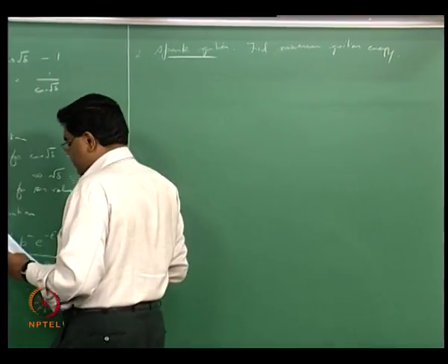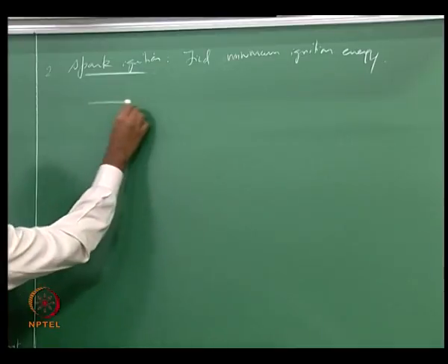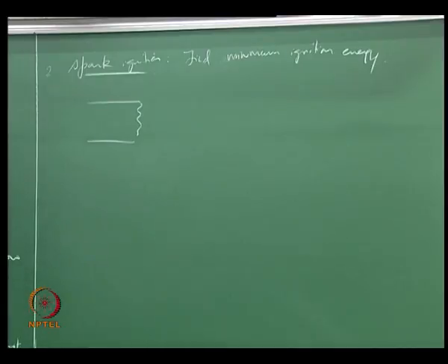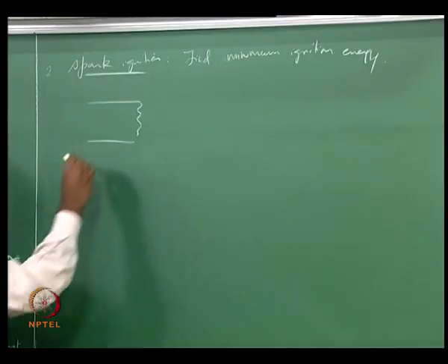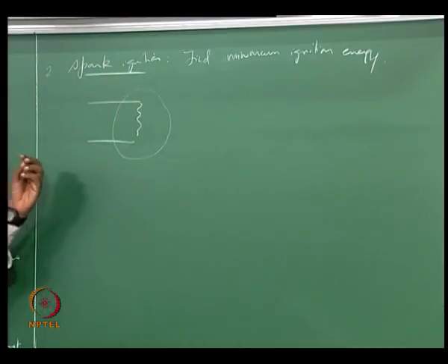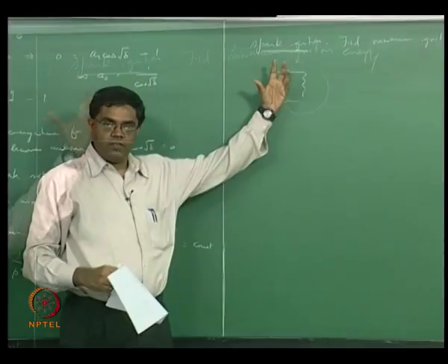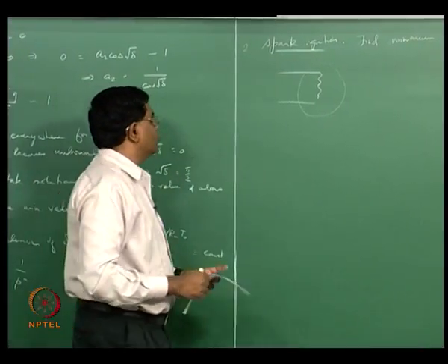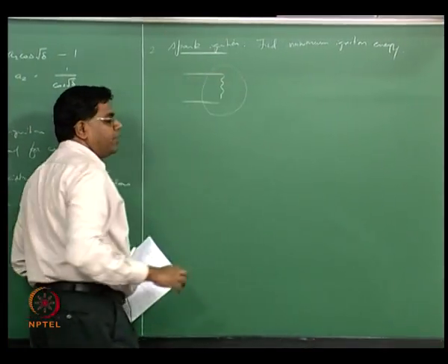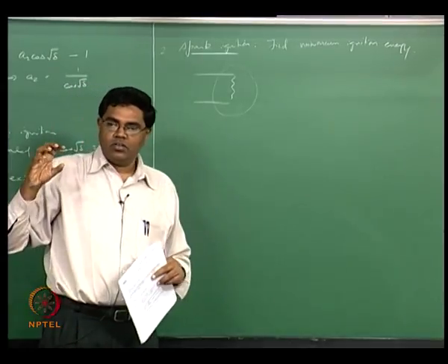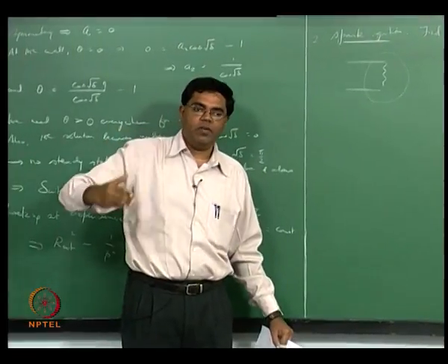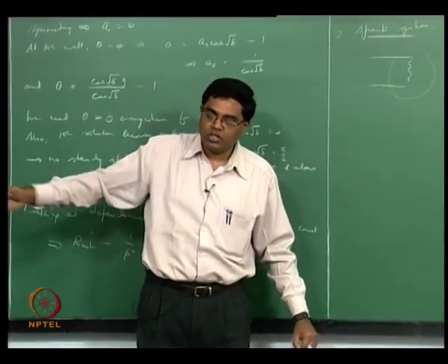right. So what we are looking for is, if you have a spark that's coming up and you have a flame that is now growing from here spherically, locally spherically, that's how it's going to happen. So strictly speaking we should be looking at a critical radius for the spherical flame that will sustain growing, propagating, instead of giving away the heat that is liberated during this ignition to the